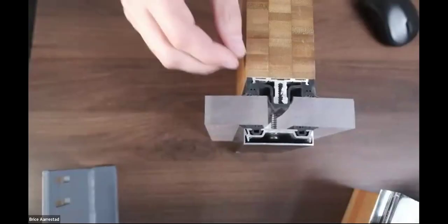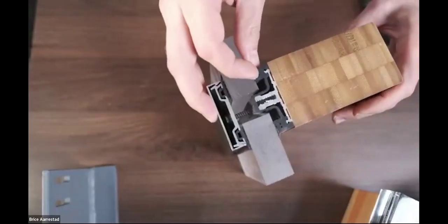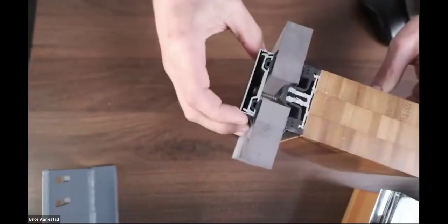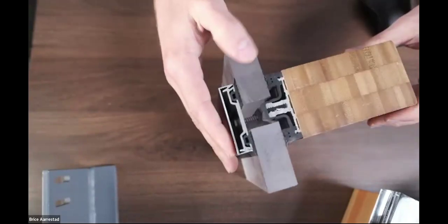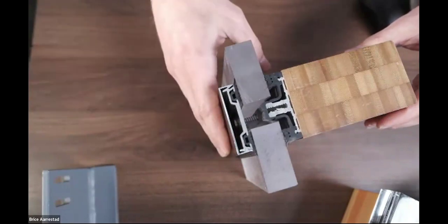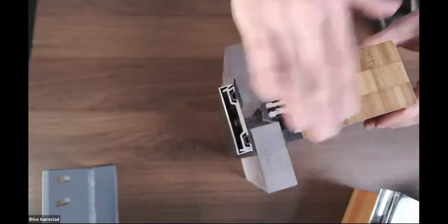All right, and next we have a two-parter. What is the service life of the gaskets, and does the gasket flap completely isolate the wood sill from the air? Thinking about the moisture. Yeah, so the gaskets are pretty robust. If you're seeing from even this view, there's a lot of EPDM rubber there. They last a pretty long time. The system is warranted to the same length as a conventional aluminum curtain wall. So generally, we're seeing a 10 or a 15-year warranty on it, but they're intended to last much longer than that.